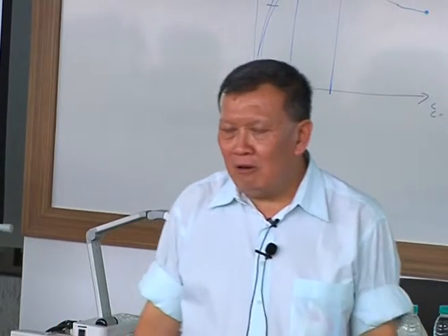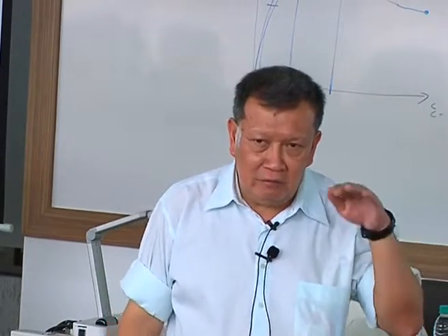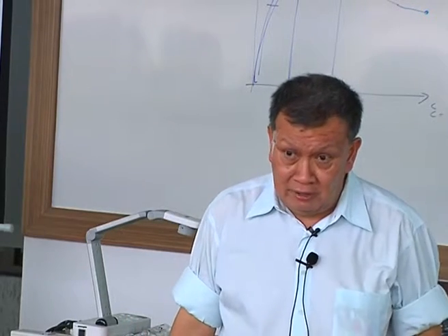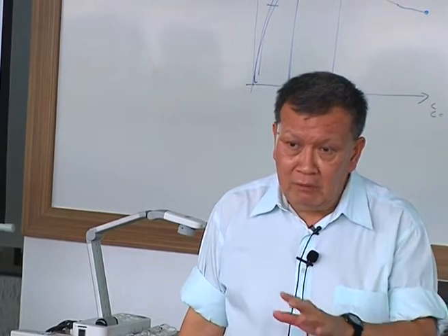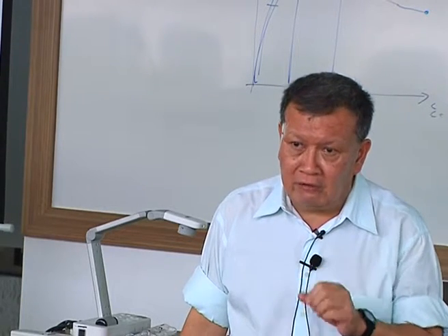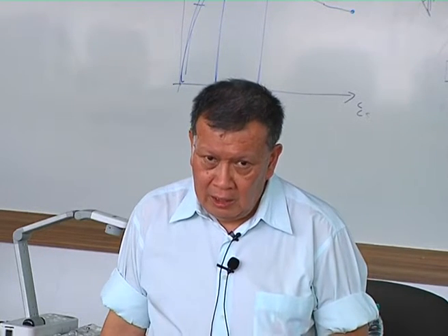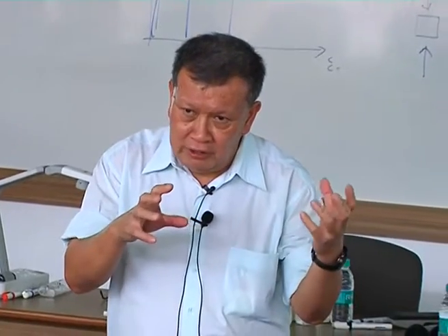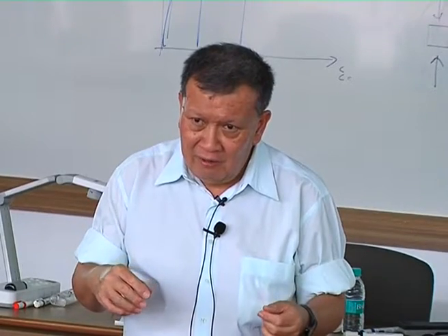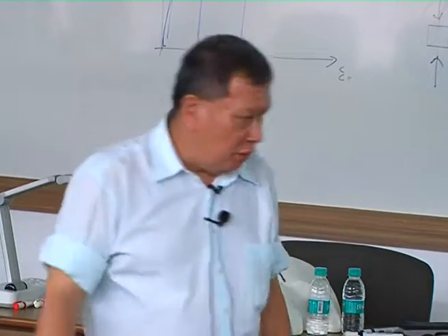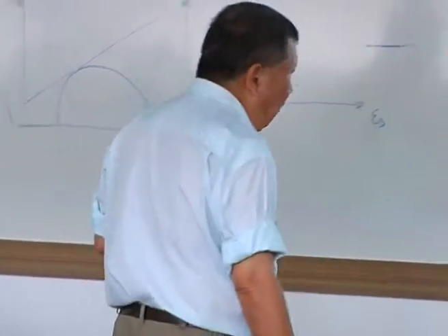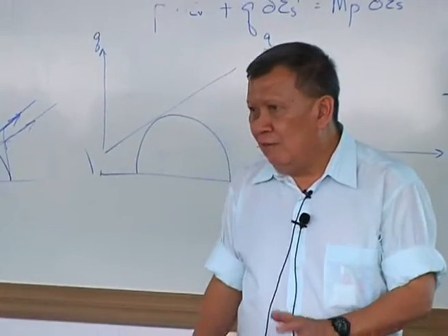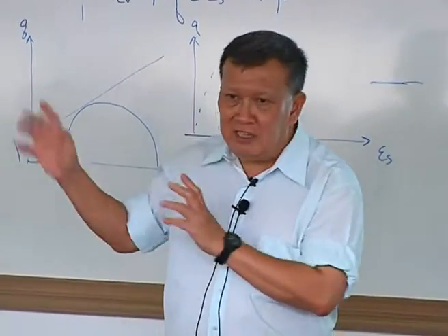But in terms of modeling, the Fort Canning tunnel went through the Fort Canning boulder bed. We actually model it as a residual soil. But I don't know whether the bouldery clay you encounter here is residual material or is it in other material? Correct, but the clay itself, is it a residual material, weathered soil, or is it soft soil or what? Residual soil, right? So it's what we call weathered residual soil, and it's quite common. I had exactly the second case study on this.